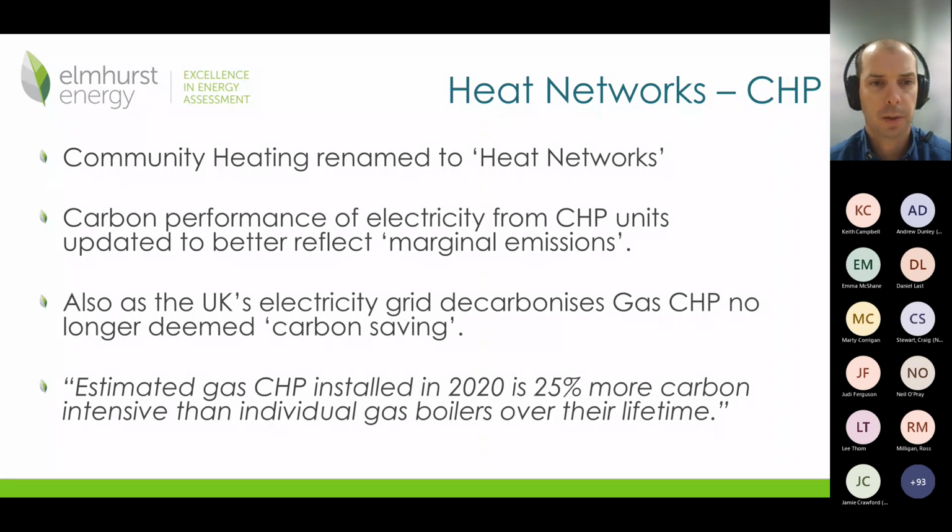CHP has changed a bit. Again, this is all about how the electricity grid's decarbonised. You used to get a very high reward for using CHP because you were generating electricity rather than using grid electricity, which was very high carbon at the time. But the trouble is electricity is no longer high carbon. So the benefit of using these systems has gone away. They actually found that they're more carbon intensive now than just using an individual gas boiler because of the effect on the gas efficiency.